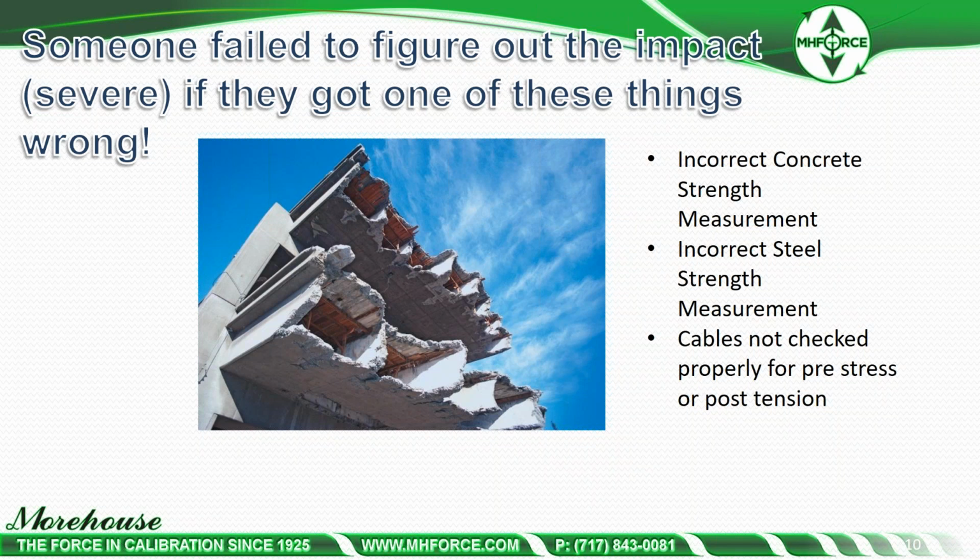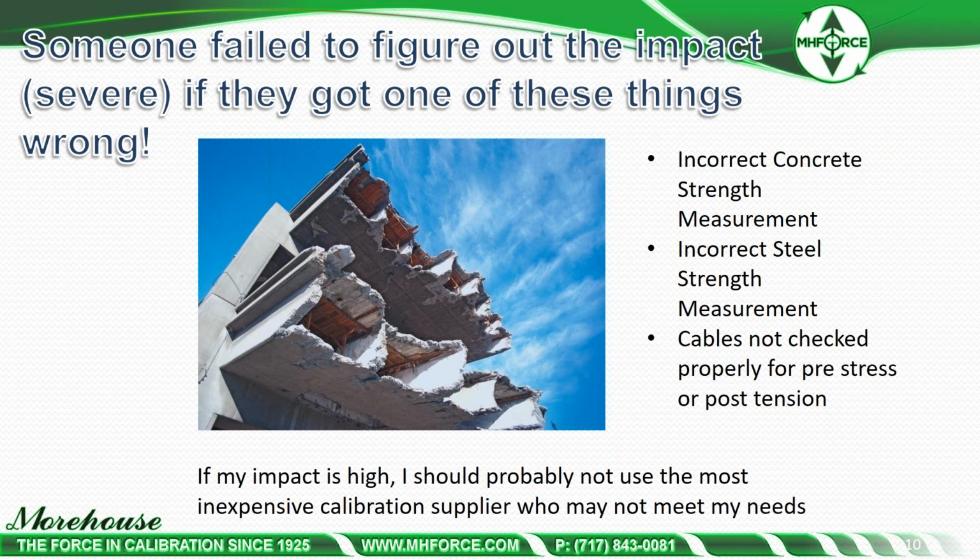They could have gotten an incorrect concrete strength measurement. They could have gotten an incorrect steel strength measurement. They could maybe not have checked their cables properly for pre-stress or post-tension. So my thought here is, if my impact is high, I should probably not use the most inexpensive calibration supplier, who may not meet my needs.